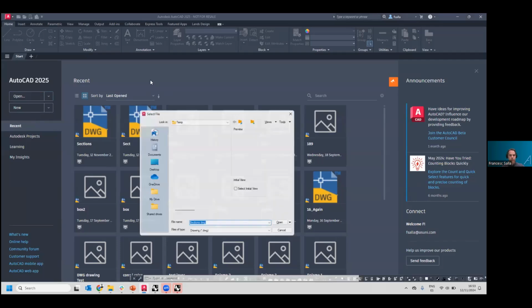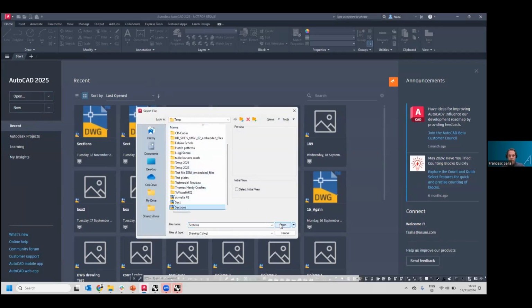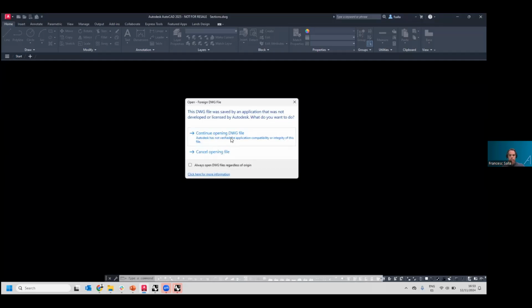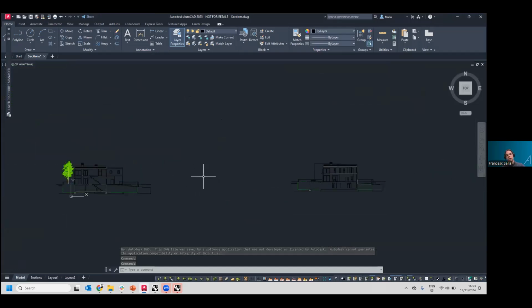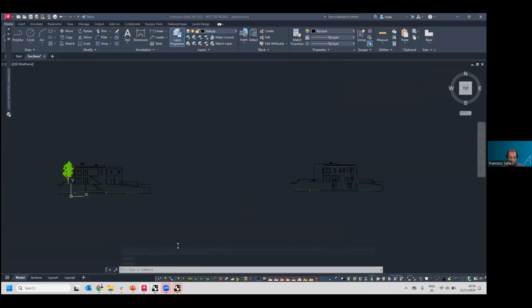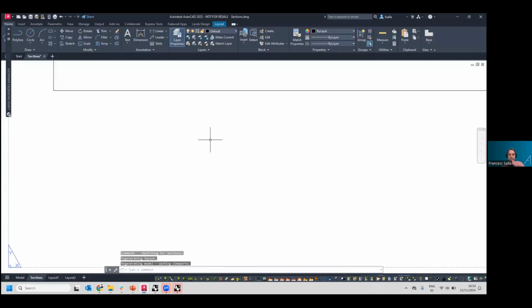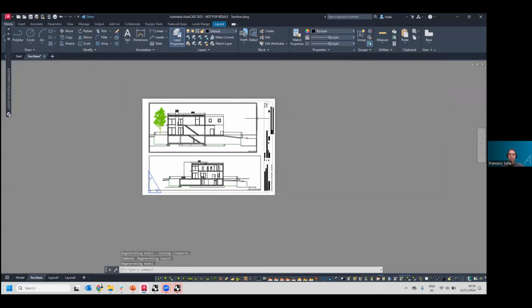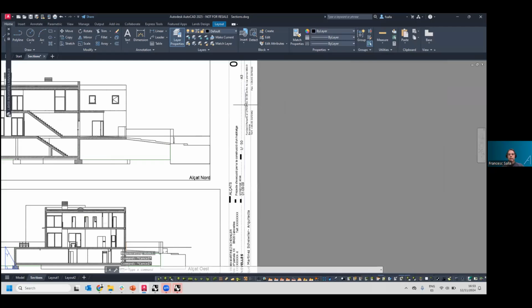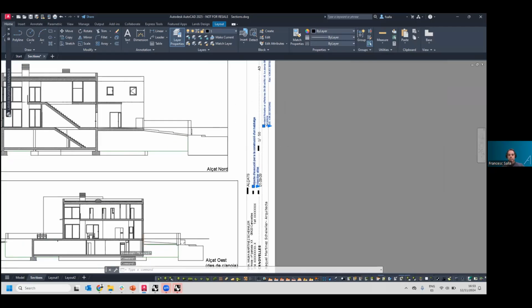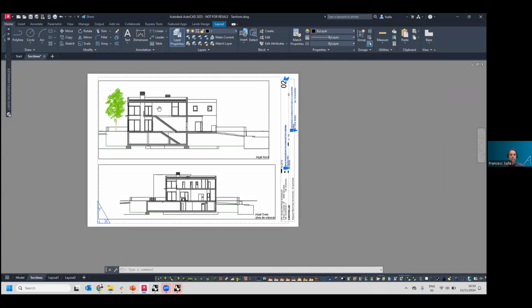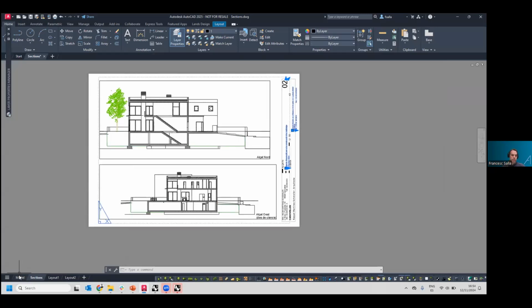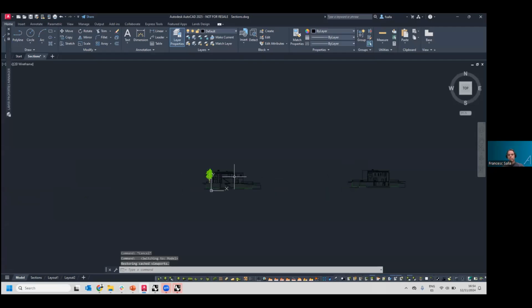So I'm in AutoCAD now. I'm going to open this model. And this is what we should see after exporting the model to DWG file. See if it has finished. Not yet. But basically, we have the same page layout in AutoCAD with two views to the model space. All the geometry in the page layout is here as in the paper space, and we have the geometry of the 3D model in Rhino as 2D drawings in the AutoCAD model space, separated for some distance.